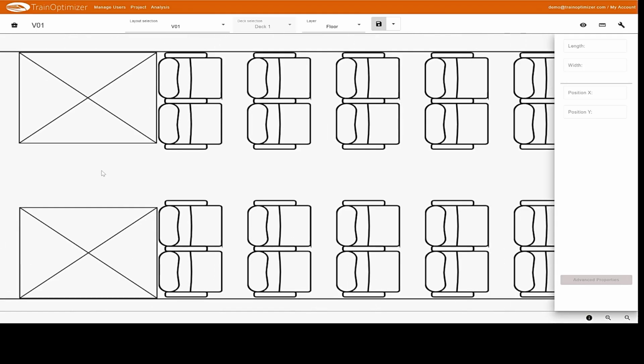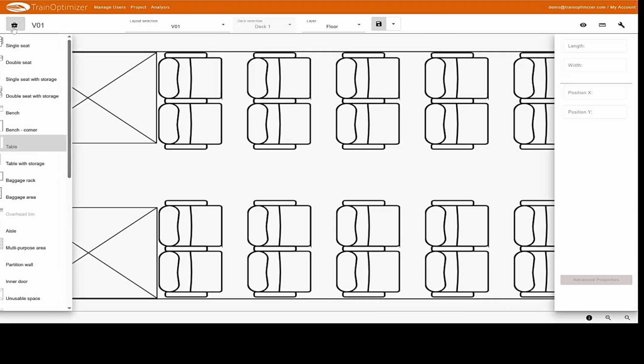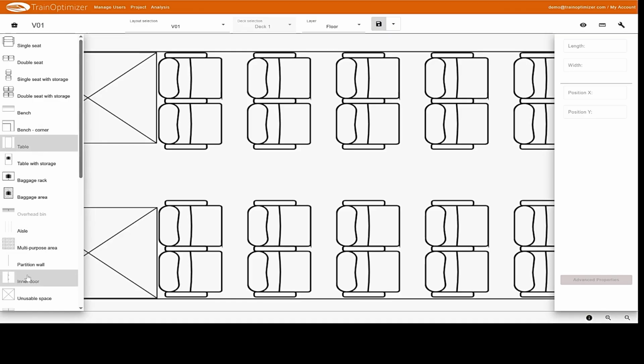You also have the option of drawing in another door for the interior area. To draw the door as accurately as possible, we use the measuring tool again and activate the snapping function when measuring.